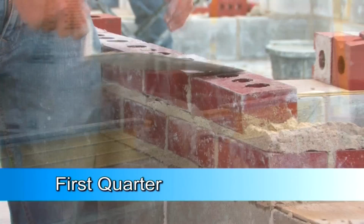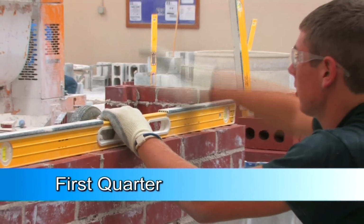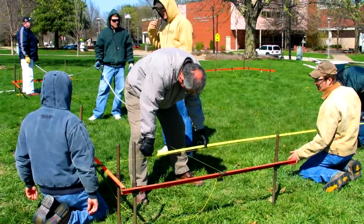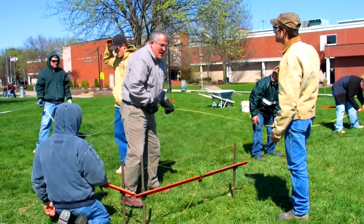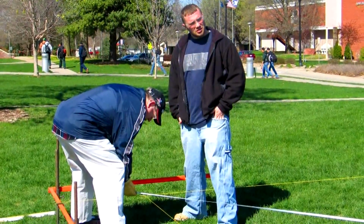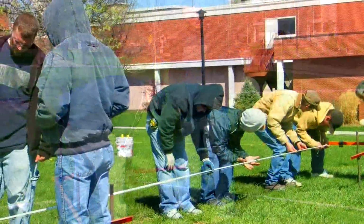During the first quarter of building construction, students start the quarter by doing a project called site layout. This project involves locating and setting up a building using the builder's level, squaring up the building using several different methods, and also using all of the tools associated with that particular layout.